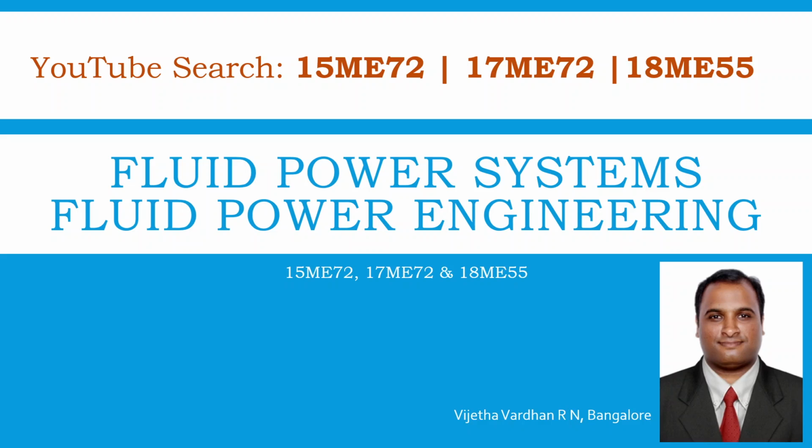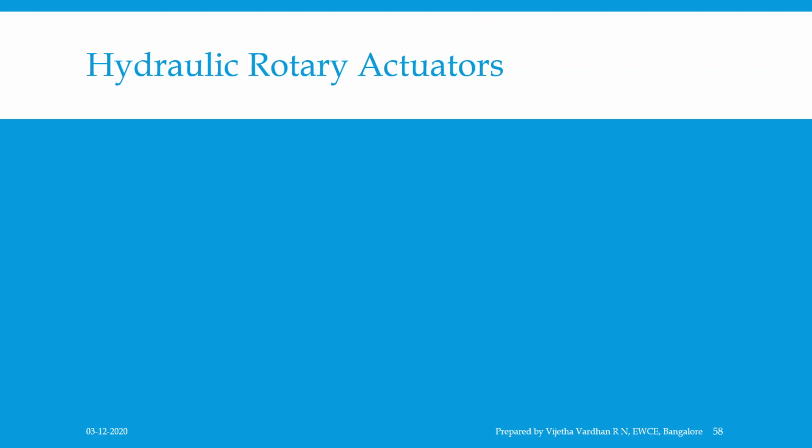Now let's start session number 20, which is on hydraulic rotary actuators. Hydraulic rotary actuators are those which convert hydraulic energy into mechanical energy in the form of rotary motion and torque. This rotary motion and torque may be used to carry out works of various nature. Hydraulic rotary actuators are commonly called hydraulic motors, graphically represented by a circle with dark arrows towards the center.